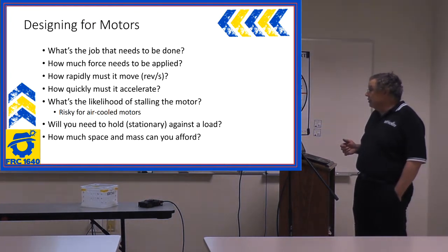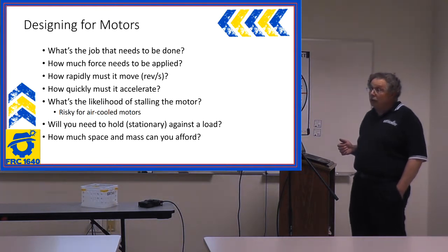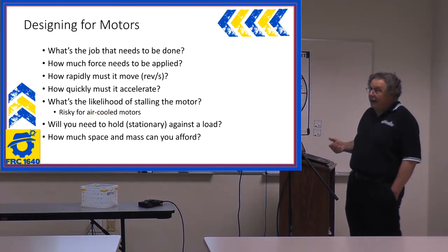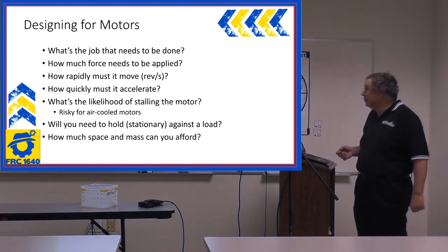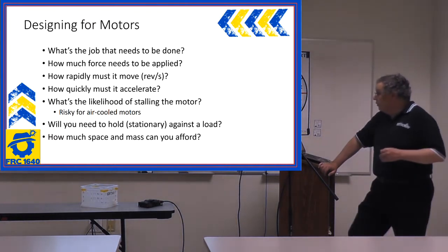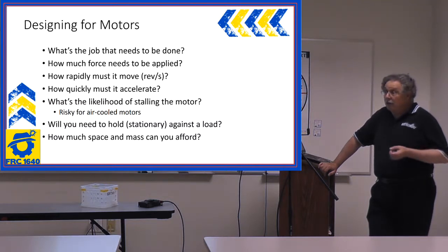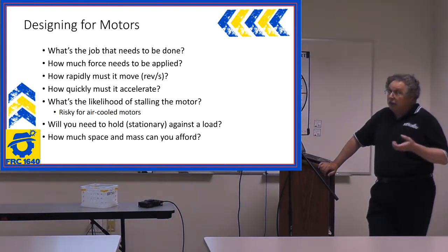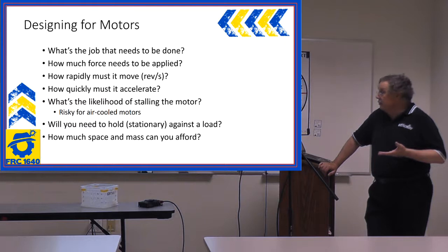What's the likelihood of stalling the motor? Because if it's an air-cooled motor and you stall it, you're going to have to change your motor, and you're not going to have that motor for the rest of your match. If you stall an air-cooled motor, you will burn it out. Also, will you need to hold something in a stationary position as part of your design? In which case, you can also rule out an air-cooled motor. You have to use a sealed motor.